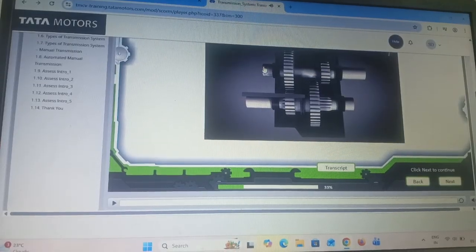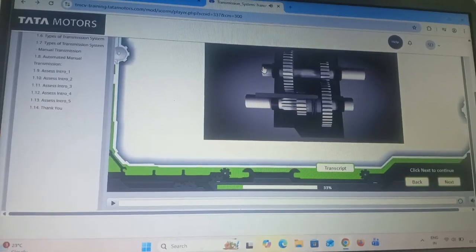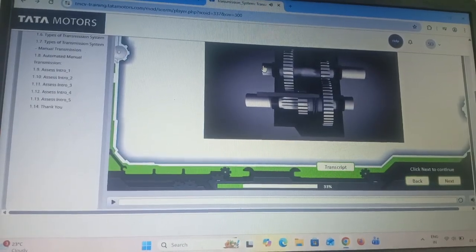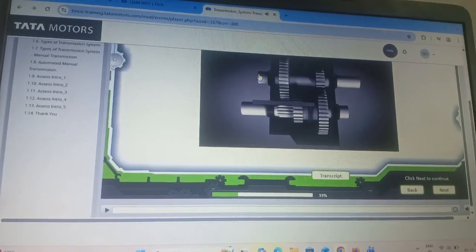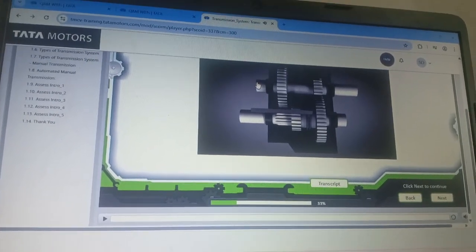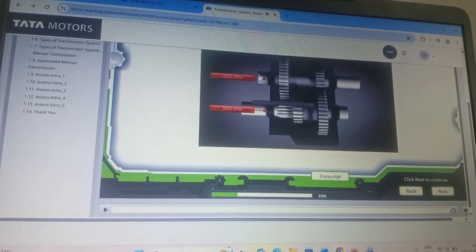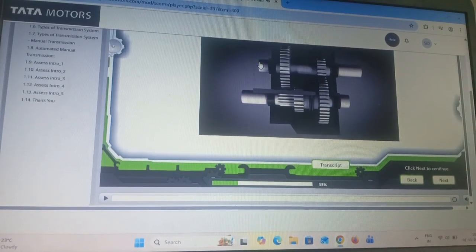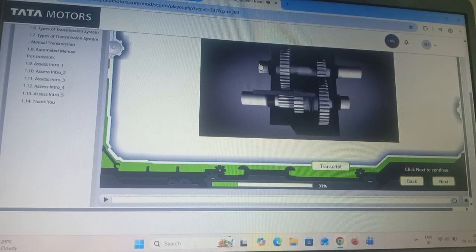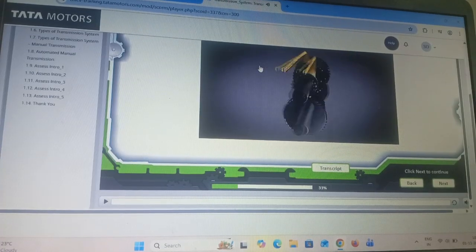Shifting from first to second gear in this transmission is only possible when the engine stops. Then, shifting of gears is possible. In second gear, the input speed is increased because the gear ratio is 0.5. Because gear shifting is complicated for these kinds of transmissions, synchronized manual transmissions were developed that allow the driver to easily select and deselect the gear, even when the vehicle moves.